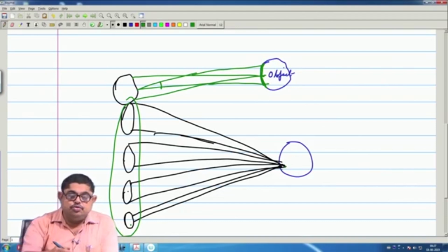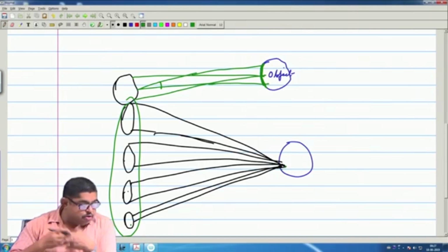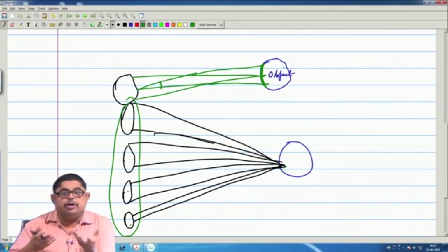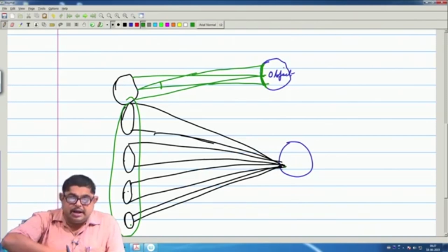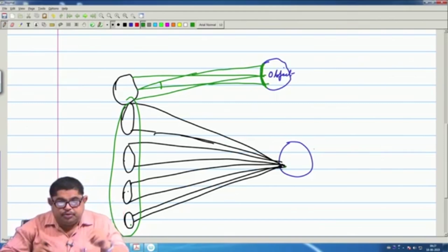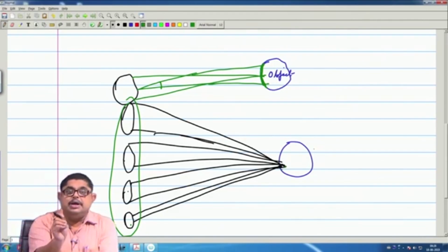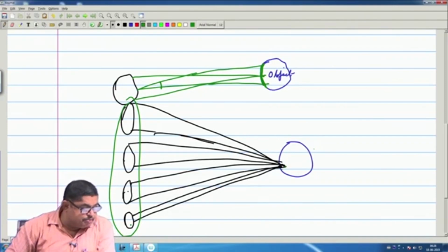Now, it judiciously compensates that phase shift and that is called coherent signal phase compensation. By that it behaves as if there was a real large antenna, very large, and from all its portion it is simultaneously sending the beam, and that is why the resolution gets improved.